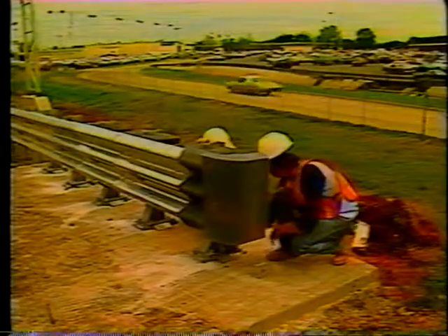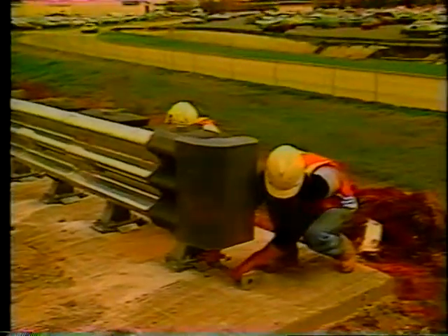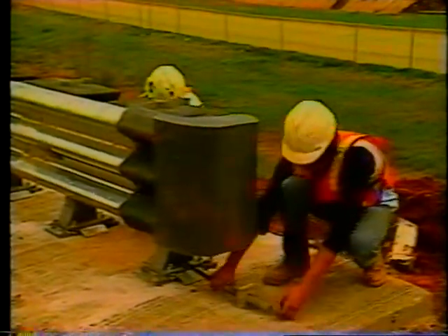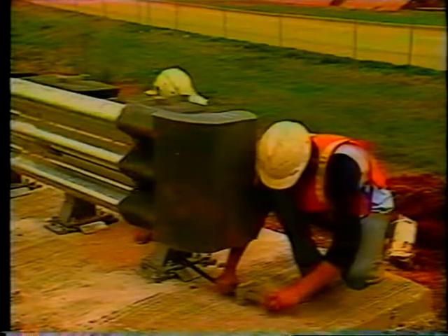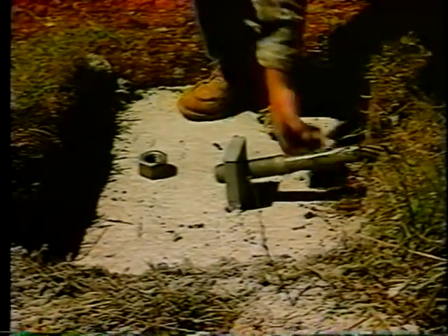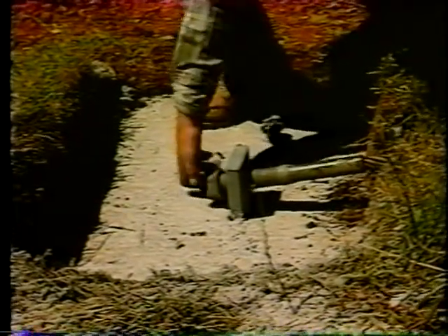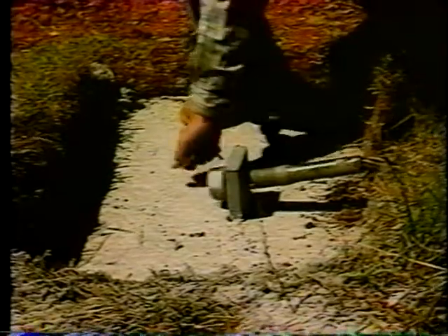The cable is now ready to be connected. Place the front threaded end through the first post and on through the anchor. Install 1 square washer and nut on it. The rear anchor threaded end must go through the rear anchor, using as many square washers as necessary to install the nut without bottoming out on the threaded section. Tighten the cable by holding the swagged end with a pipe wrench and torque the nut with a torque wrench to 100 foot-pounds.